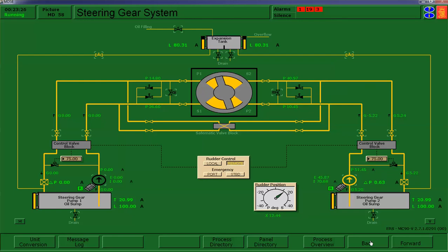Now, while we're waiting him to do that, let's talk a little bit about this unit. This Safematic. You notice that both of the sumps, this is different than what you have on the Bear. Both of these sumps are flooded from the expansion tank. The idea being, if there was a hydraulic leak, this expansion tank would automatically supply oil to the sump to compensate for any leak.